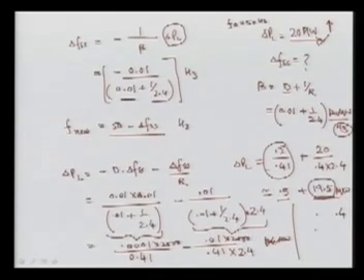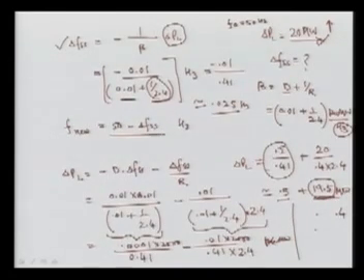If your D is very small, meaning there is no change, then it is met only by the governing action. So now we have calculated the steady state frequency, and we can see what the steady state frequency will be. By assuming this component is 0.4, here 0.01 with the negative sign, minus 41. Approximately, the value here is 0.025 hertz that we are going to change. So the frequency change is no doubt very small, but that is also the load that is met by these two components.